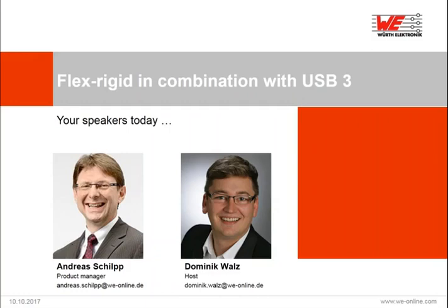Okay, so to be honest, I don't know exactly what the standard specifies, but regarding vibration in general, if you have external impact on the system, Flexrigid has a big advantage as the flexible areas which are doing the connection between the rigid parts have a very low physical mass.